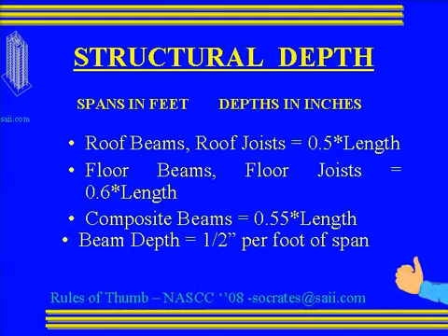So it depends, when you first start, you always have, what do we call them? Not fudge factors. What did I call them, John? Well, the 1.2, what did I call it? The uncertainty factor. You have uncertainty factors. So you can do your best analysis that you can at that time, even if it's analyzing a 52-story building and you come up with how many pounds per square foot, because you don't know what you don't know at that time. So you put a factor when you give it, and then as the process goes, as you learn more, as you feel more comfortable, the factor becomes less and less. In the end, it becomes 1.